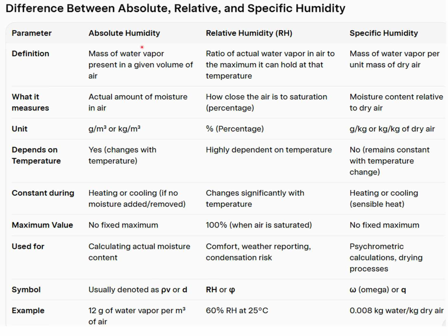Absolute humidity is the amount of water divided by volume, that is, per unit volume, how much moisture is present. Relative humidity is the percentage in regard to saturated air. And specific humidity is grams divided by kg, where the amount is measured in kg. This is the basic difference.